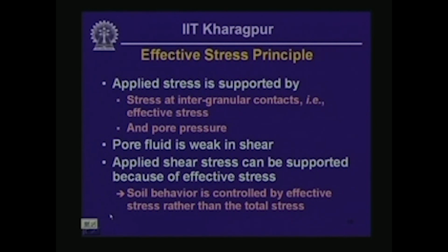Okay. Now, we look at the effective stress principle. Applied stress on a saturated skeleton of soil or rock is supported by stress at intergranular contacts and pore water pressure, as we have seen already. Since pore fluid is weak in shear, if we apply shear stress to the specimen, it can only be supported because of effective stress.